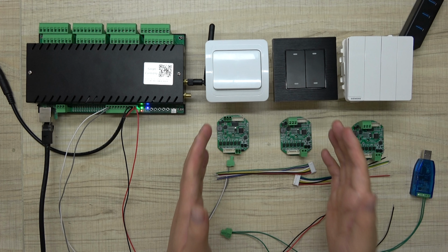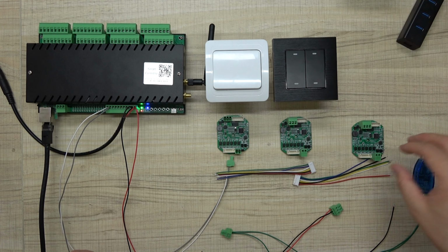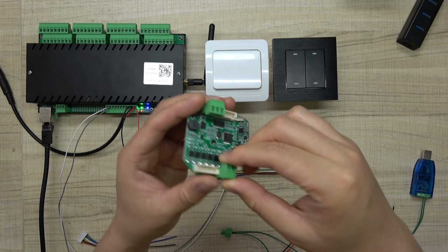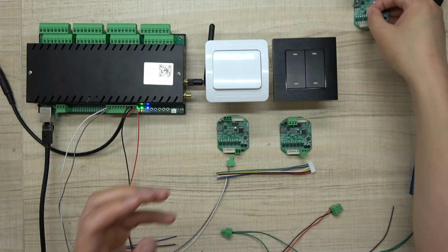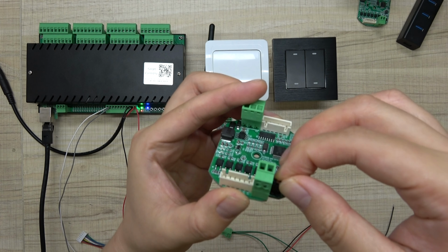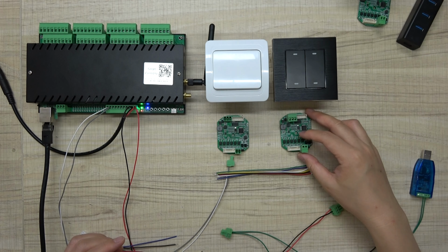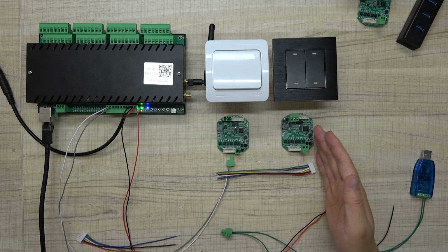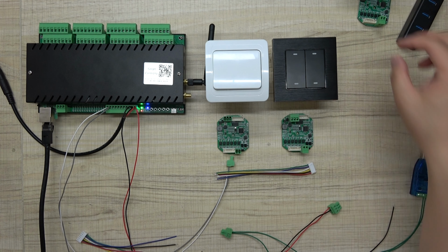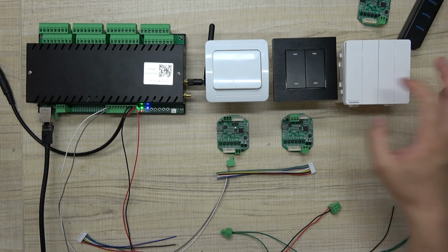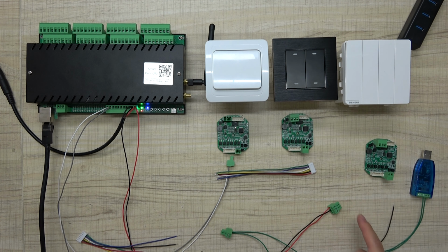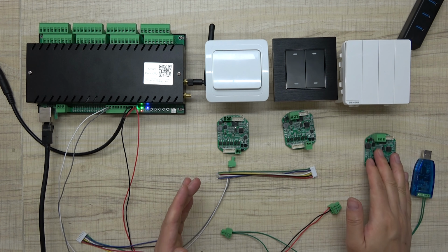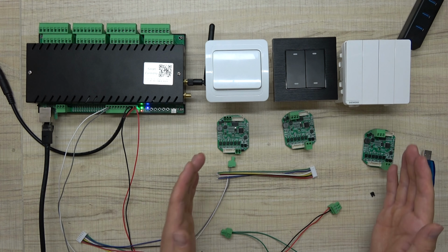If you have only 2 switches, just remove this one and not this one. Only these 2 switches. So you should remove this jumper and connect it to these pins on this board here. So the resistance of the RS485 must be enabled at the last terminal. Maybe if you have 3, maybe if you have 4, always use the last one. The jumper always goes on the last one. So that will let the RS485 bus work stably.